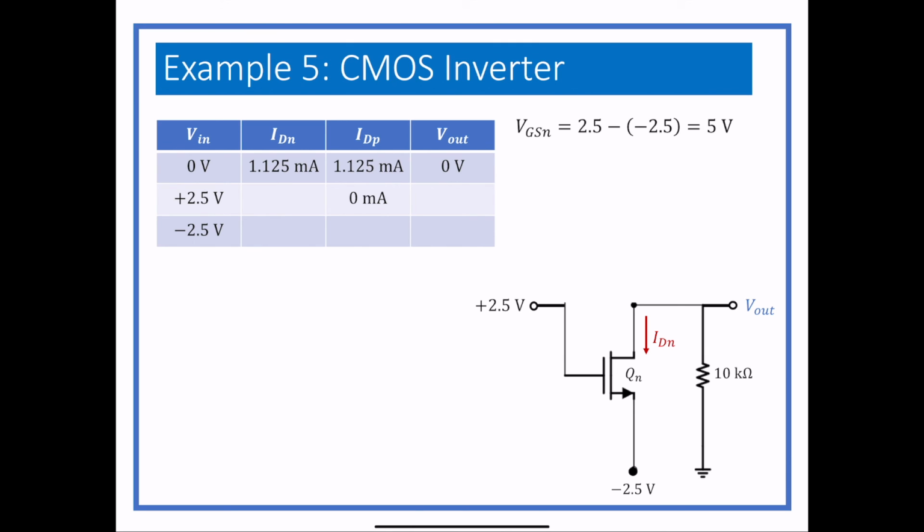And the drain current, we're going to use an approximation just to make it a little easier. But remember, in the triode region, the drain current depends on VDS as well as VGS. So the drain current is approximately equal to Kn over 2 times VGS minus the threshold times whatever VDS is, which we don't actually know what it is.